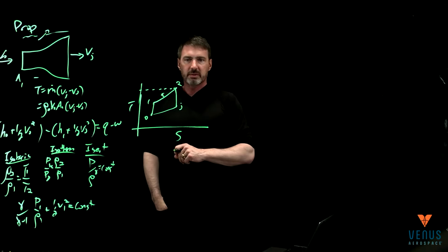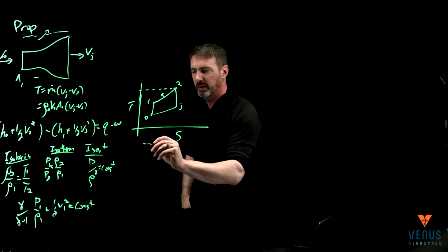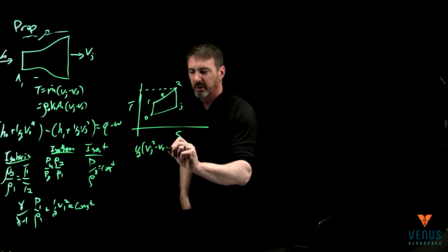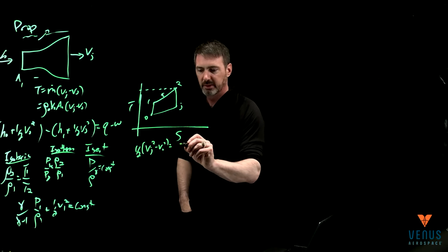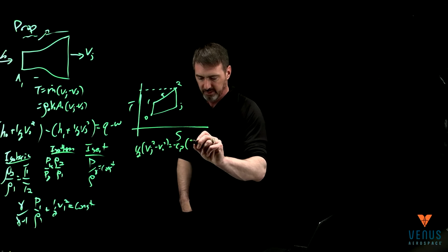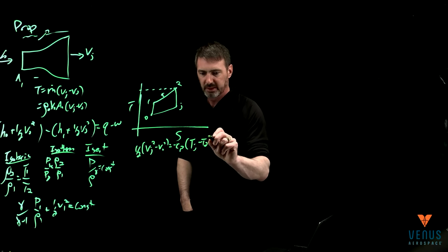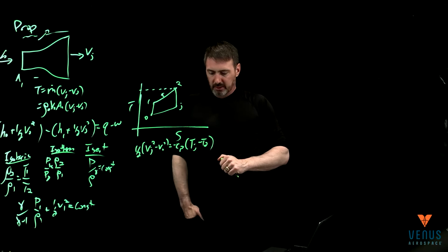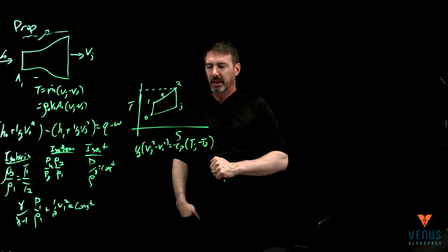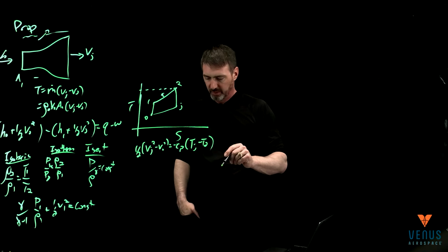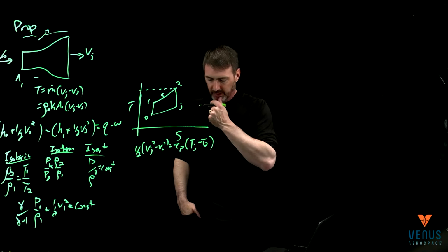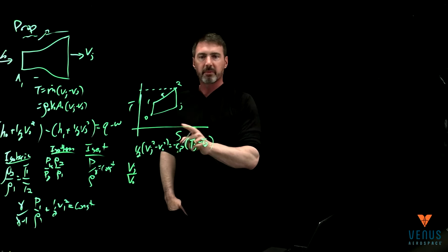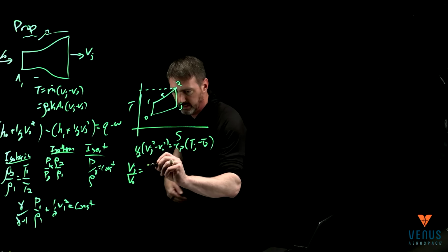From a conservation of energy point of view, the difference in kinetic energy, V squared, is going to be Cp, with a negative there, times T jet minus T2. Whatever I'm able to convert is coming from that heat addition, and we can solve for the relationship of the jet compared to the free stream from this equation. So I'll write that down.